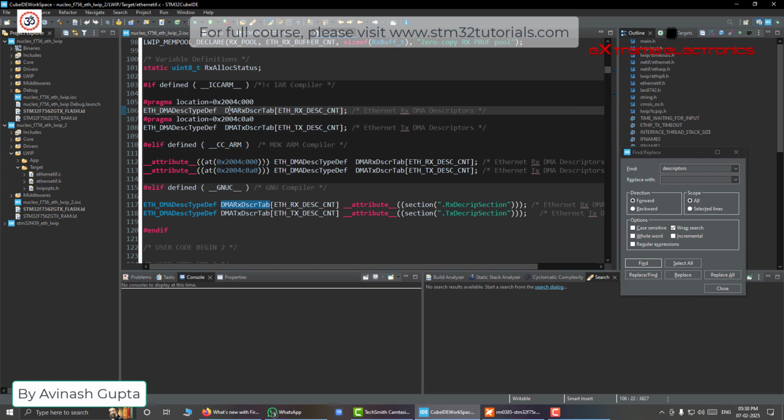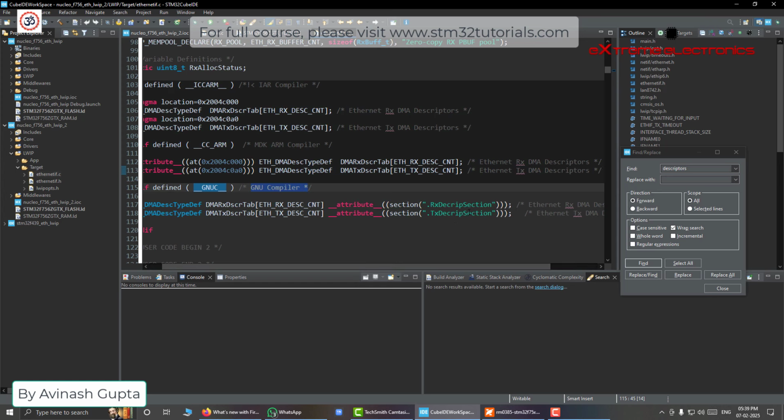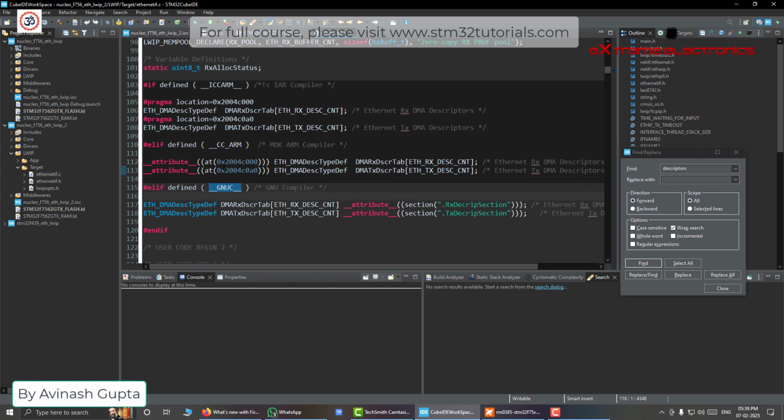And the same is the case with this Keil MDK compiler. It uses this attribute, the @ attribute. So using this @ attribute, they are directly able to place this array in this location, and this array in this location. But we cannot write such code directly using the GNU C compiler. It only supports specifying a particular section. So they are not using directly hard-coded memory addresses like they are using in the case of the IAR compiler or the MDK compiler.